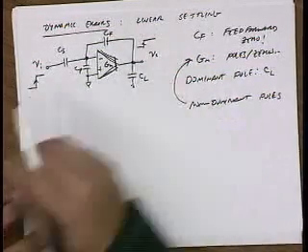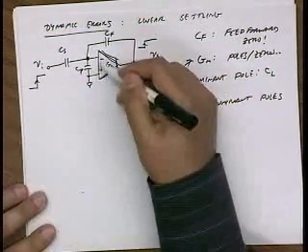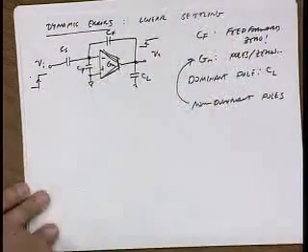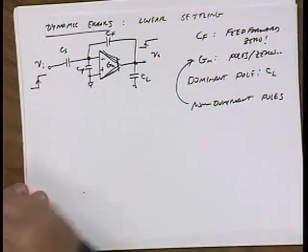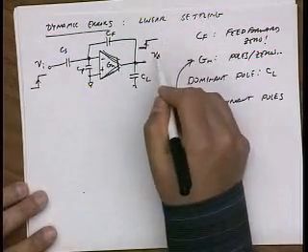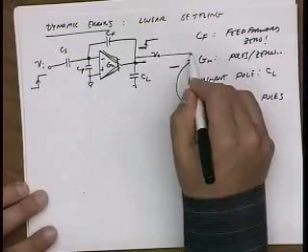Well, once the amplifier wakes up, what does it do? It sees that there's an error voltage at the input, and feedback will drive that error voltage to a small value. In fact, because the output has gone in the opposite direction, this is an inverting amplifier, so the final value is somewhere over here, where this is 0.